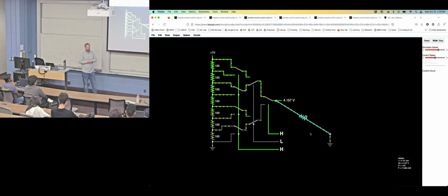What would cause, I guess, in a real world application, this kind of disruption? You put a speaker on there, a little 16 ohm speaker on the output of your DAC, and it's going to brown it out. It cannot drive enough current to keep that voltage there. Right? And so that's why you often need a power amplifier. It's just another little IC that will amplify that signal to make sound.